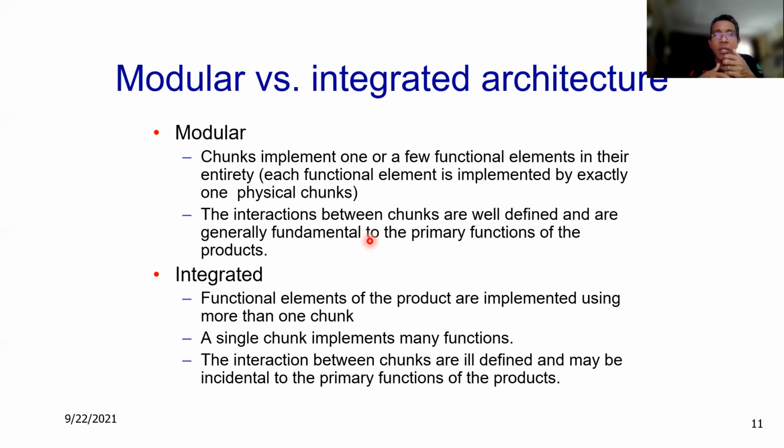So you cannot simply make an improvement for one function only. You need to take all those chunks, because they are related, the gear with the brake. So you need to take them out, do the improvement on them, and consider the improvement for the whole part, and the part cannot operate without that chunk. So they're not independent, they are integrated with each other. So that is the difference between modular design and integrated design.